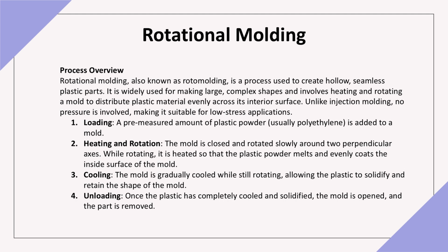Plastic powder is added to the mold. Heating and rotation. The mold rotates on two axes while heated, distributing the plastic evenly along the interior surface. Cooling. The mold cools, solidifying the shape. Unloading. The part is removed.